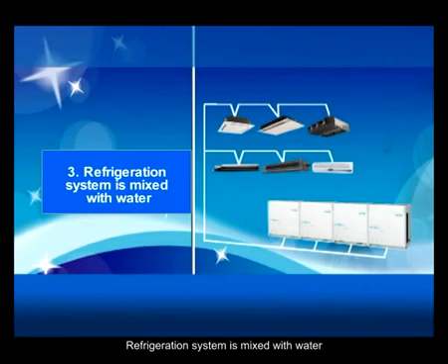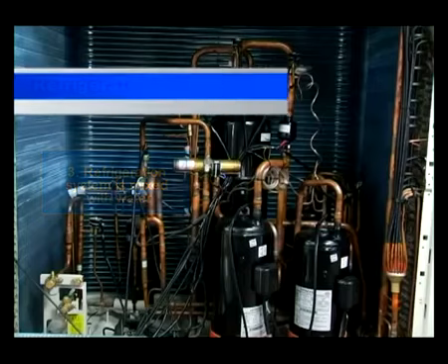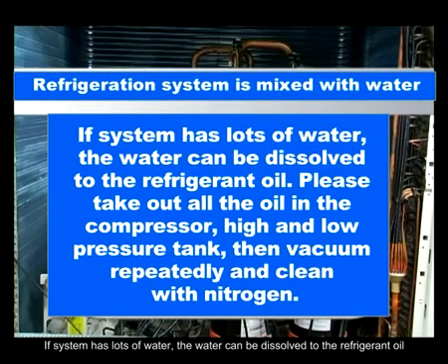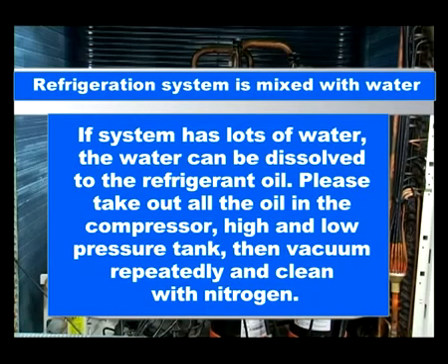Refrigeration system is mixed with water. If system has lots of water, the water can be dissolved to the refrigerant oil. Please take out all the oil in the compressor, high and low pressure tank, then vacuum repeatedly and clean with nitrogen.